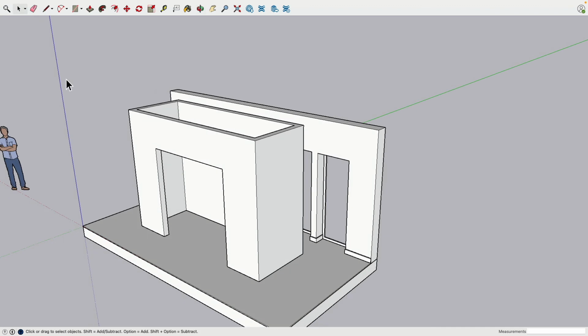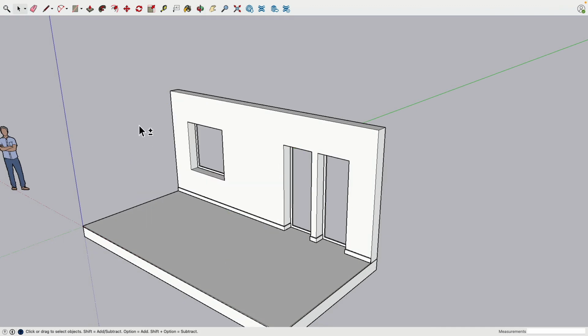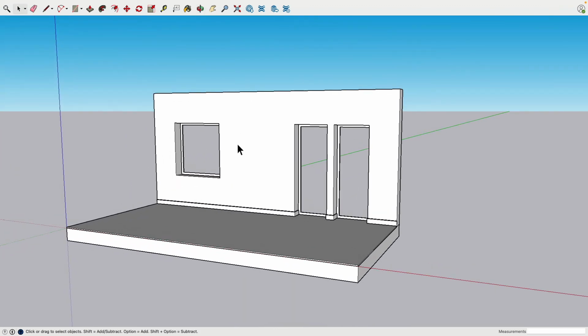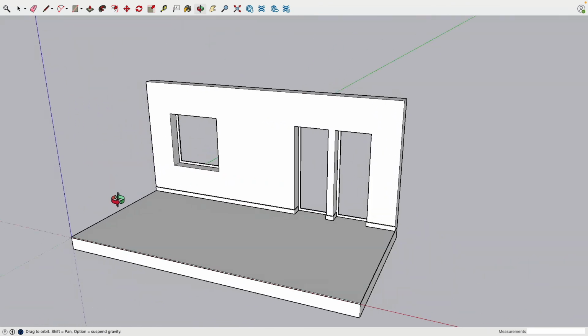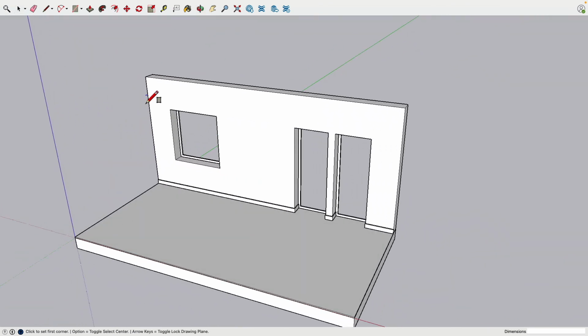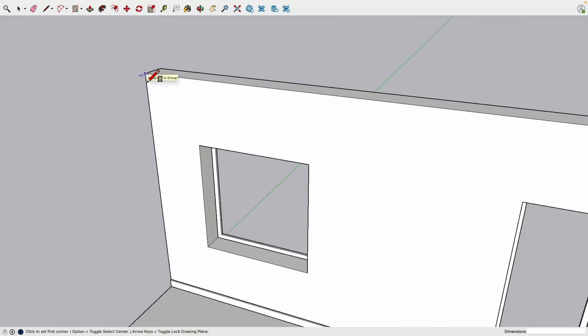So actually that's the beauty of SketchUp. The modeling techniques are very simplistic and can be applied for all types of geometry. We just need to understand what type of geometry an object we would like to build is made of. So we're getting close actually to the end. Let's add an interesting detail. So we're going to open the ceiling and expose the joists.